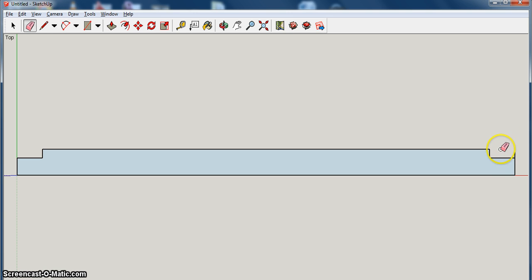So now I've got my side, it's 235 millimeters long, and we have a 4 millimeter rebate where we can take the ends of our drawing into each particular part here. Of course, the purpose of having our timber joints is we have a greater support when the piece of timber is held in, and also it gives us a greater gluing surface area. So we have glue along the side and also along the end of the joint.